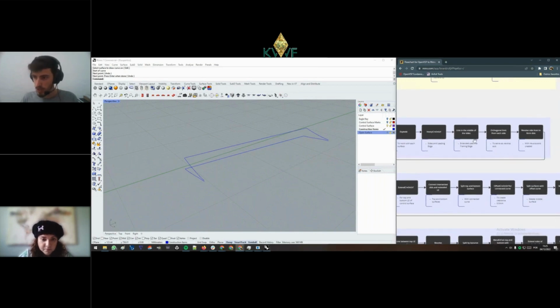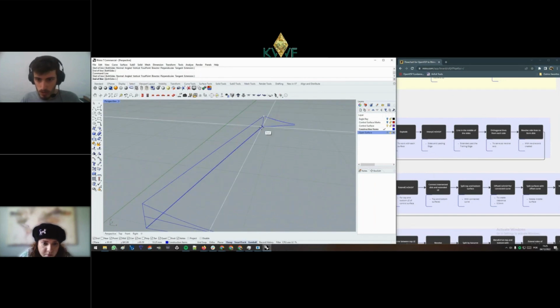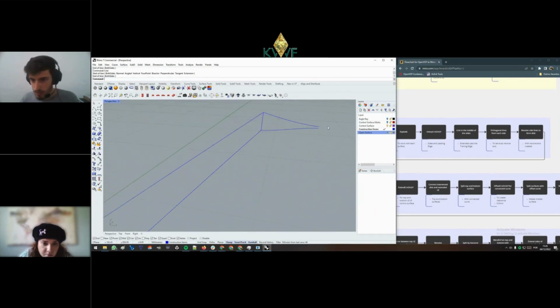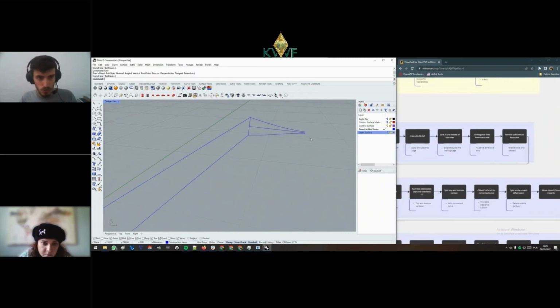So here's the step I'm going to do now. It's a line in the middle of the sides. So I'll use the line command. We'll close it, both here and here. And this is the line in the middle. This will be used to create the side of the control surface later. And I will extend this line past the trailing edge to revolve later using the extend command, just selecting it and extending an arbitrary amount.